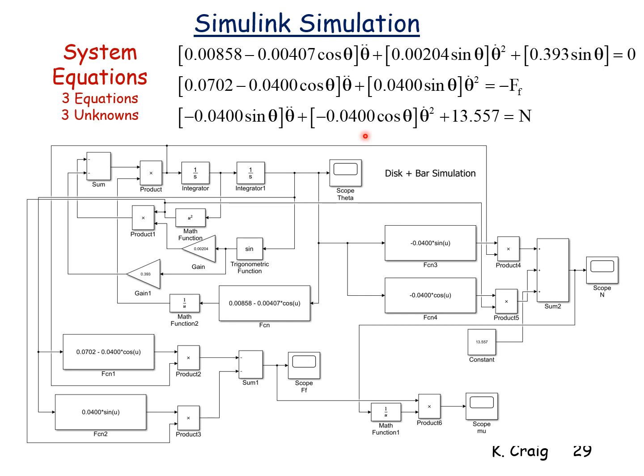Always keep the parameter values as variables because if they do change, you only then need to change them in one location, which would be a MATLAB M file. And then that change will propagate throughout all of the equations and all of your simulation diagrams. I'm doing it here but just for expediency and to make the diagram a little less complex.